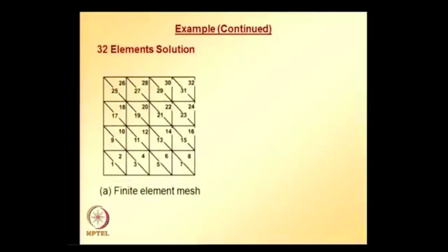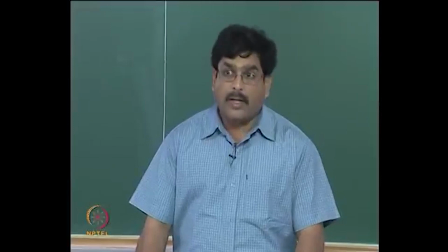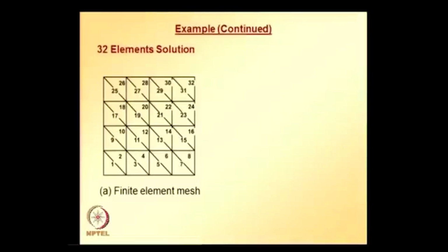and the finite element discretization is shown. Everything is similar since all elements are identical. Finite element shape functions or finite element equations are going to be same for all elements, and again applying the condition that stress potential value along the boundary is equal to 0, and we get the reduced equation system.